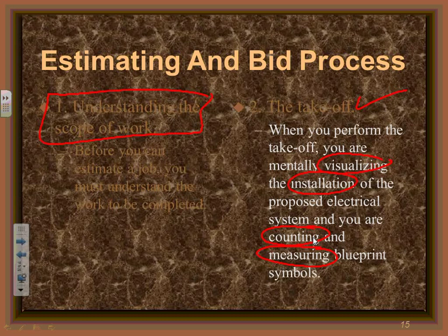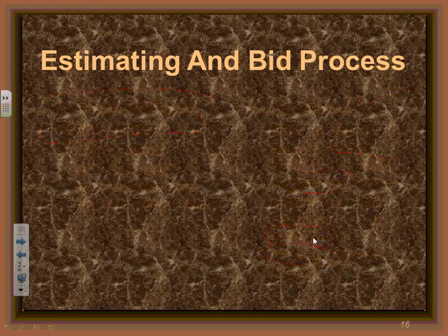Adam, you started counting these components and your fixtures, right? And with these forms, you're doing takeoff. I don't know how many of you guys have started measuring the blueprints. Anybody started yet? Then you're going to draw, visualize, go up, over, and down, assign distances, and add them up. That's measuring. So what is takeoff, Karen? Measuring and counting: counting electrical components and measuring distances. That's step 2. Shall we go to step 3?